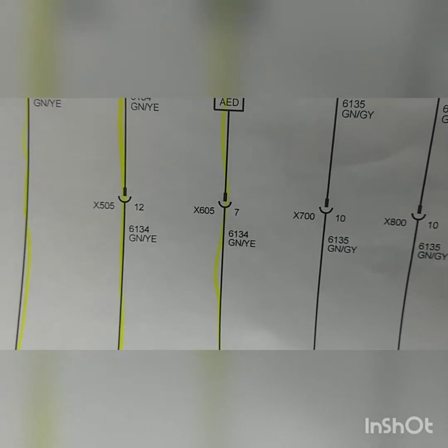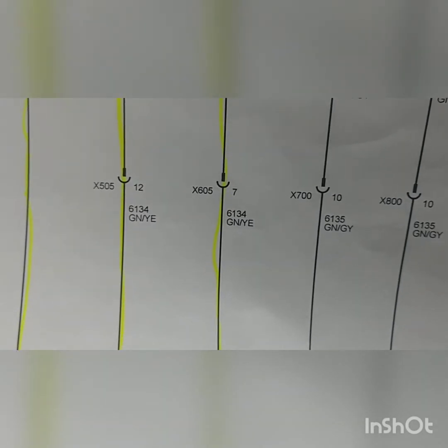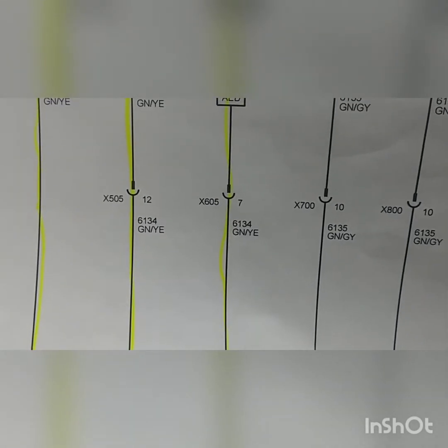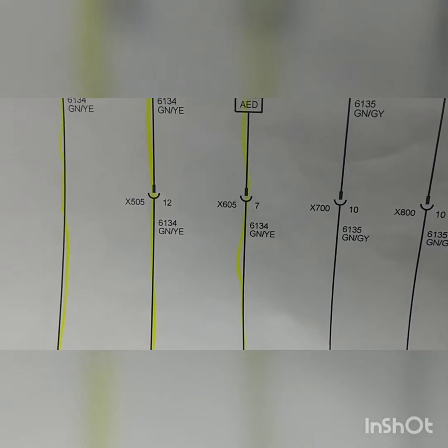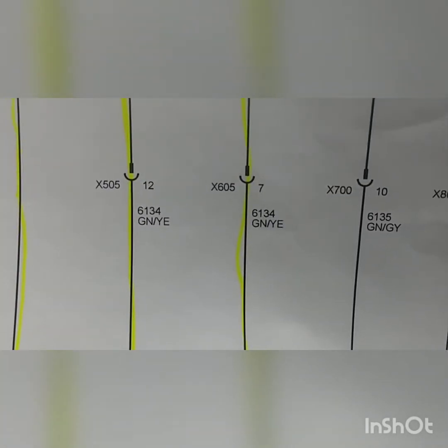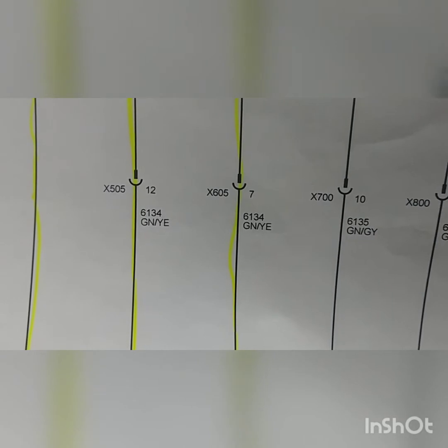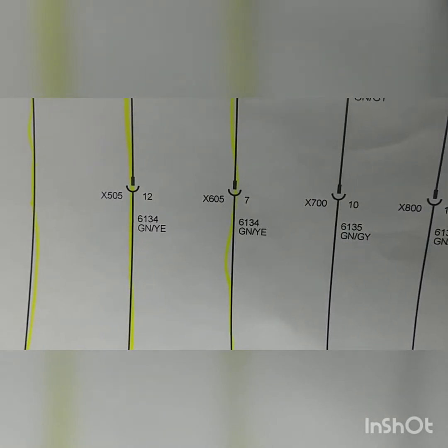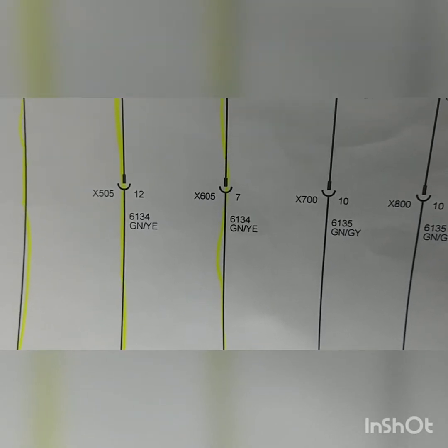The system went back on circuit, up to system voltage, and all our power windows started to work normally again. So I concluded that connector 605 on pin 7, as you can see, had high resistance, causing the inline circuit to obviously crash.